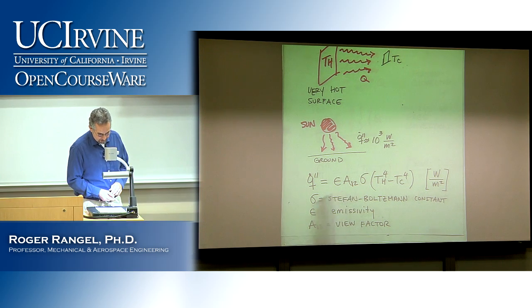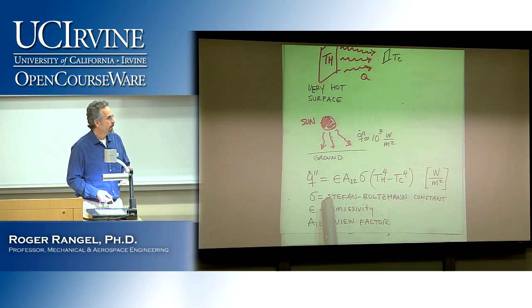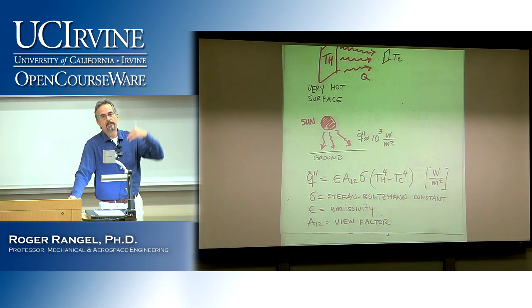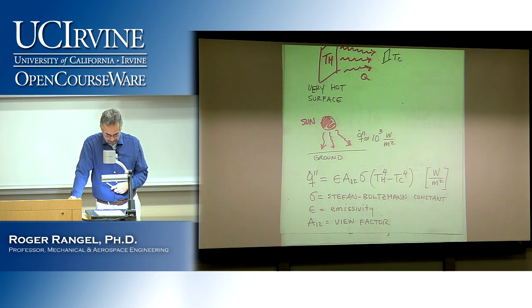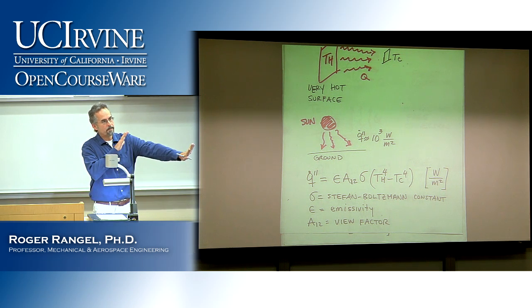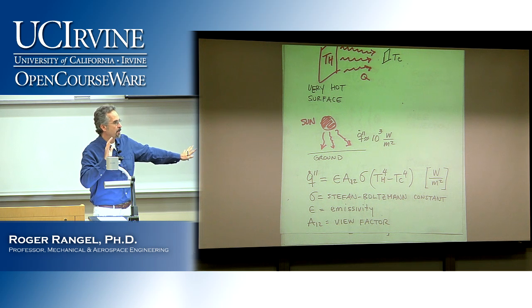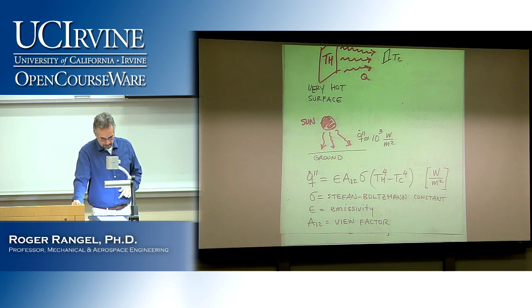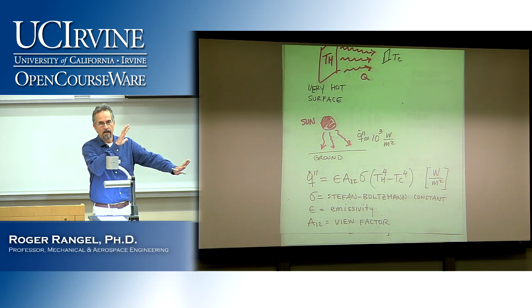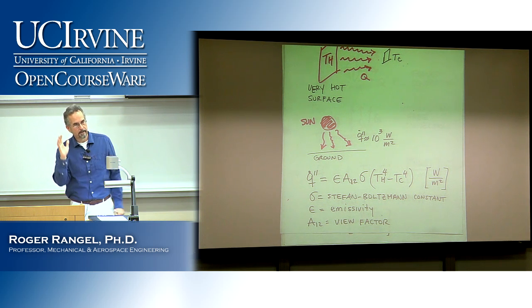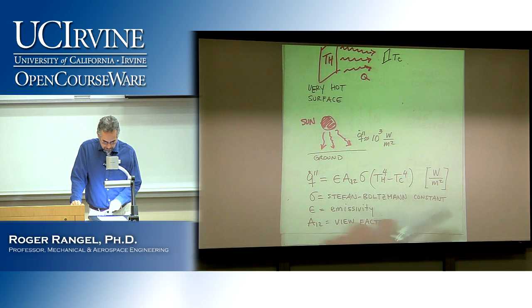But then you have more things. You have, for example, the emissivity, which is a property of a material, of an object that is emitting that radiation. And you also need a view factor, this A sub 1, 2. It's essentially how much of one object is seen by the other object. Obviously, because if the object is not visible, then there won't be any radiation. So A12 is called a view factor, and it has to do with how much of one object is seen by the other object, say by the receiver, transmitter. But then we can compute it like that.